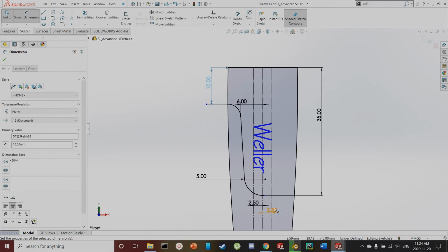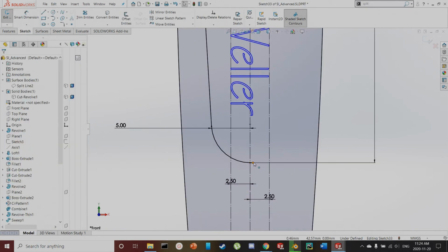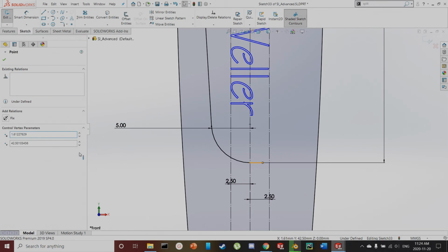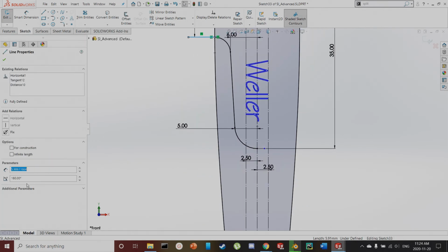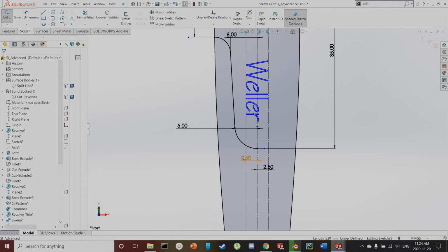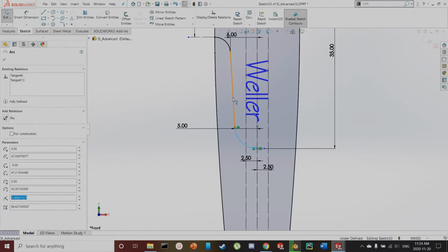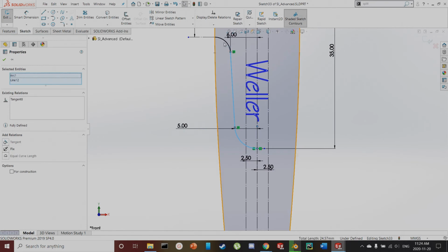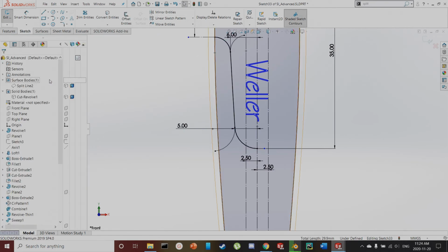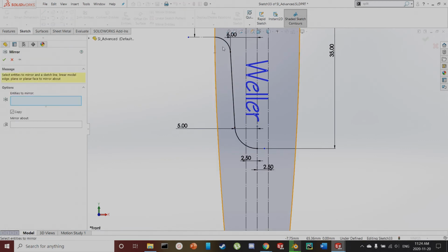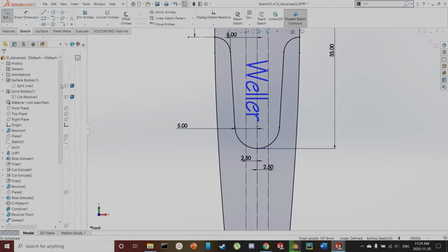That looks fine. Great. Now, I'm going to make sure that this is construction and that this line up here is also construction. And now I'm going to mirror these 3 lines. Mirror entities. Oh, okay, I'm going to pick mirror first. It tried to automatically mirror across the straight line that it found, which isn't good. Pick these 3, mirror about this line. There we go. Perfect.